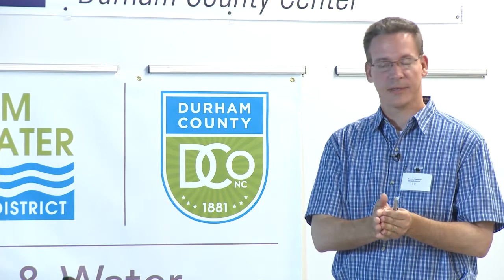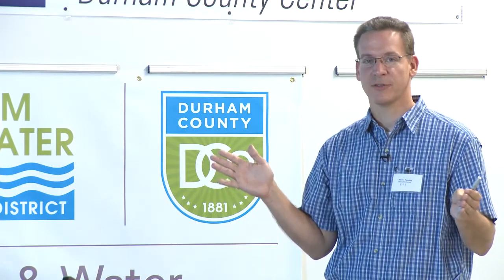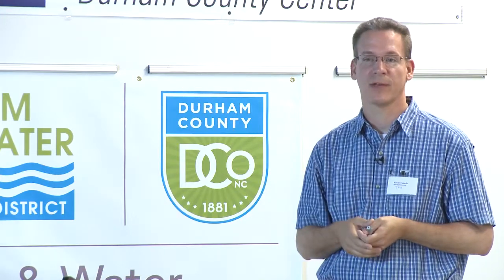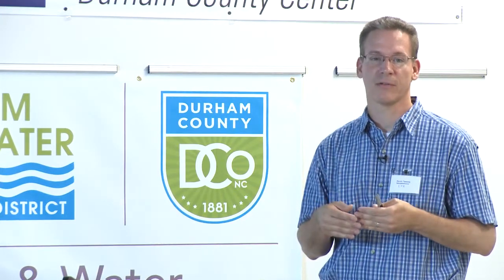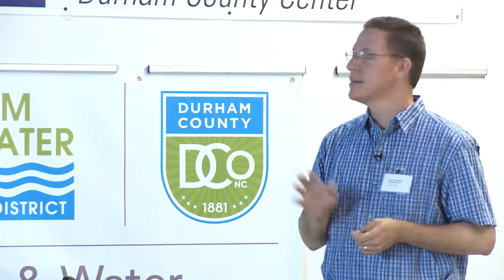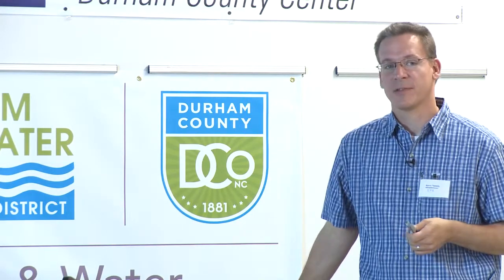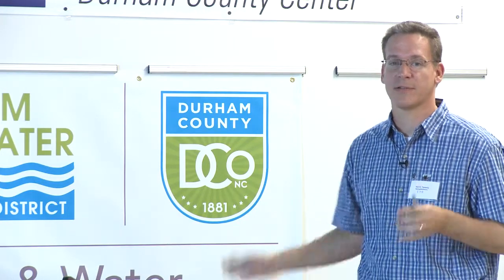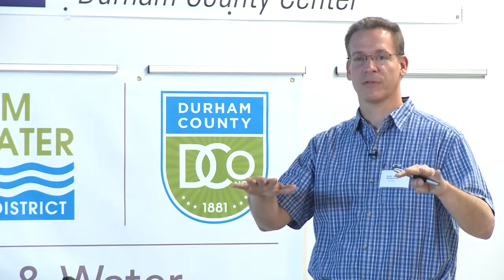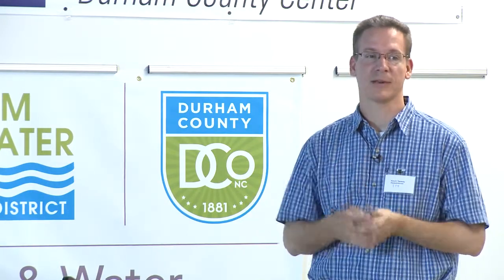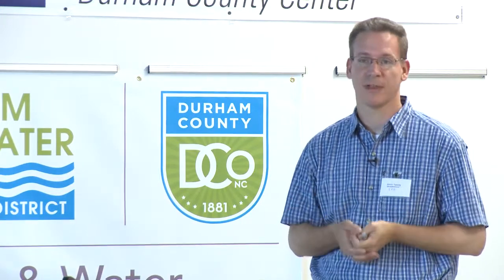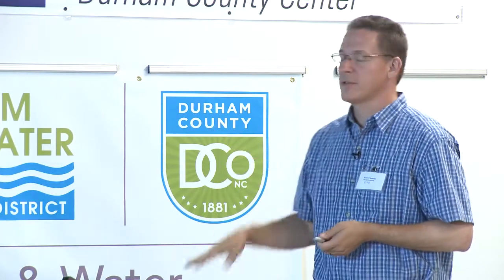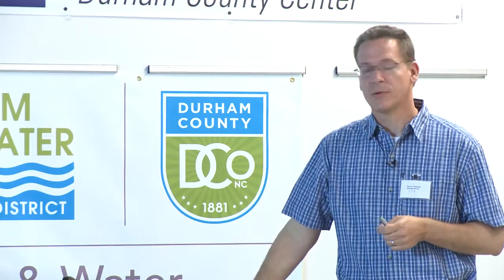So on that site, we're going to be dealing with everything from single thread channels up to maybe second order streams, all the way up to the watershed divides, where we've got ephemeral channels that are really going to have no channel form at all. A lot of wetland features in the watershed, so actually all the systems that we're going to restore are going to have wetland function to them in some context, either associated or adjacent to single thread channels, or perhaps they're just going to be flowing wetlands with no defined channel form as you get further and further up the watershed.